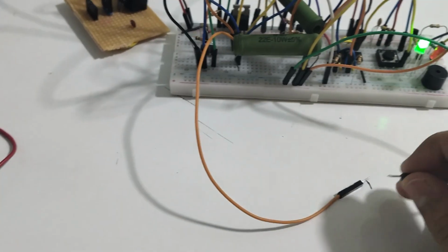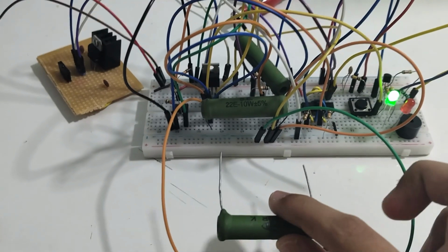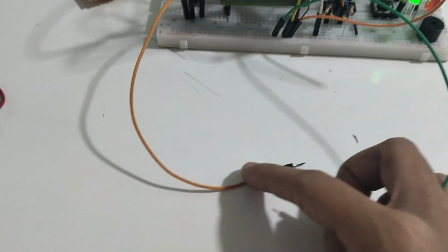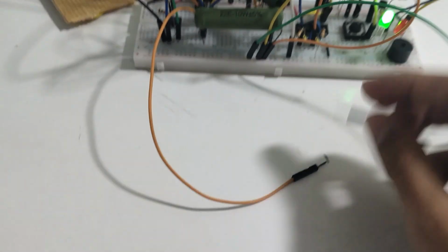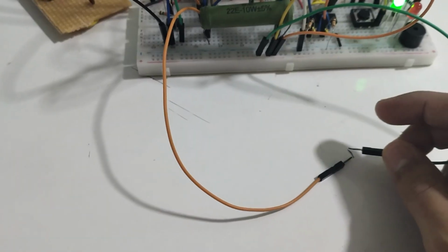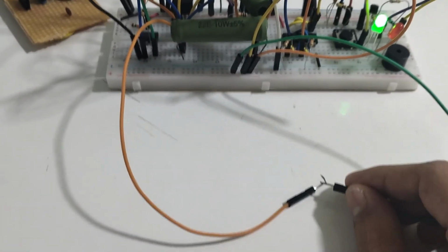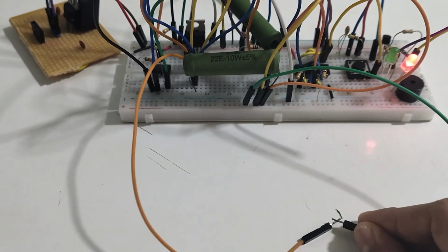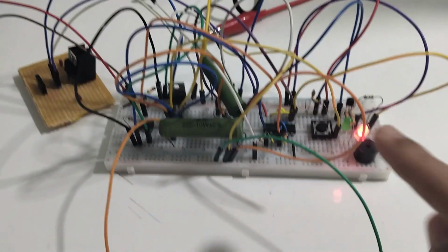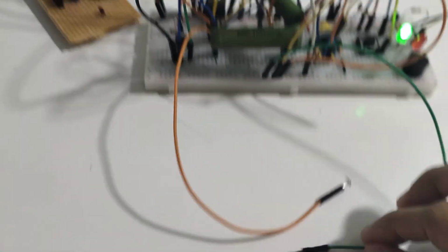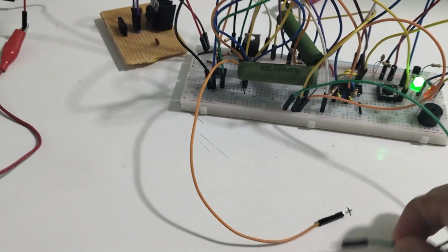And let's say there's literally a short circuit over here. The current was definitely above the rated current, but it wasn't a short. So we have these two wires, which are in parallel with the normal load. If you short these, this is going to be practically 0 ohms. So to simulate a short, I will just touch these two together, and you can see that it would still be triggered. Here I'm going to touch this, and you can see that the output has cut off again. So yeah, it can protect against both overcurrent and short circuit.